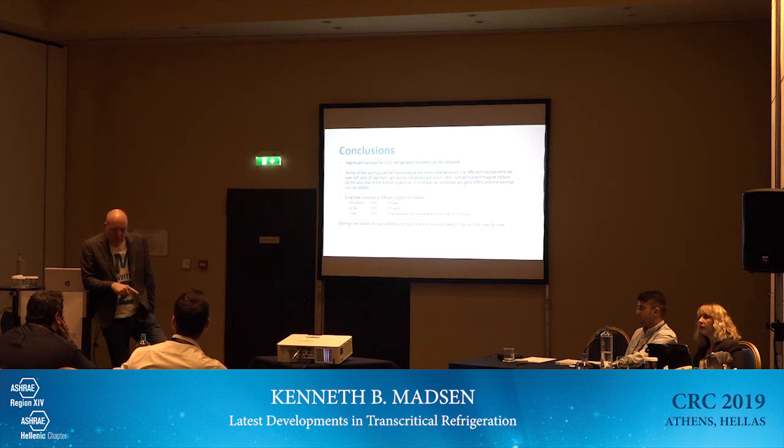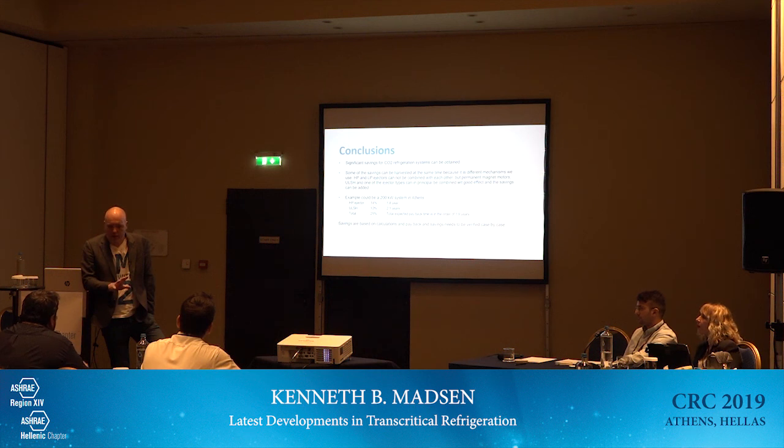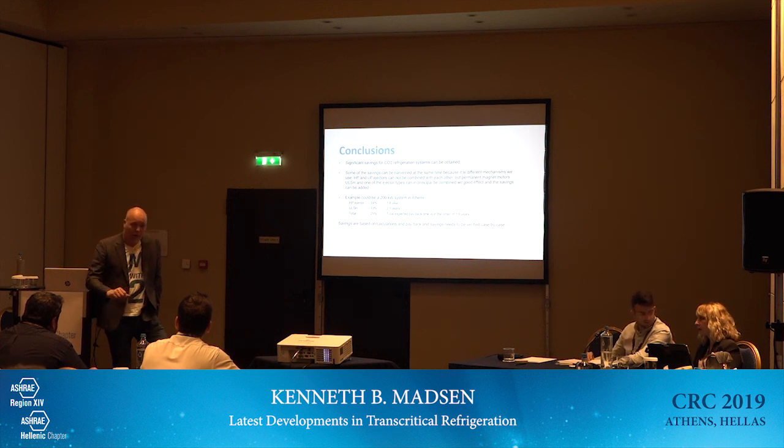Now, I was developing this system when I was at Advansor, so I can describe in detail how Advansor is doing it, but how the others are doing it, I don't have that deep knowledge. The way Advansor is doing it is that they have two sets of set points in the controller. One set point is for 1 Kelvin superheat without basically any safety. That means they allow the controller to go below 1 Kelvin without throwing the emergency brake or anything like that.